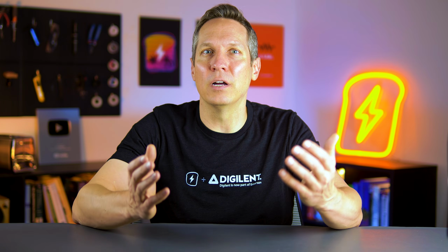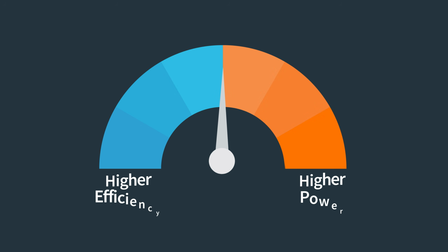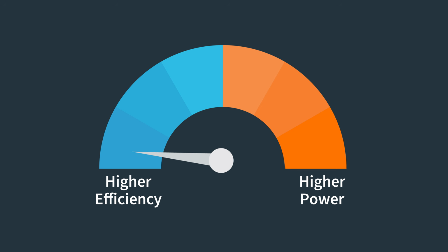This is where it depends on the situation. What matters more, higher efficiency or higher power transfer? So, in communication systems like radios, matching impedances between transmitters and antennas is essential. That's how you get strong, clear signals, because you want maximum power transfer even if it's not the most efficient. This is generally the same approach with audio amplifiers as well.